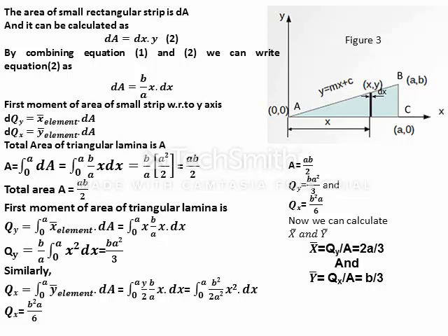For the purpose of integration in the upcoming steps, I am substituting y is equal to b by a into x in equation 2. That is, equation 2 is dA is equal to dx into y, where I am substituting y as b by a into x. Now equation 2 can be rewritten as dA is equal to b by a into x dx.